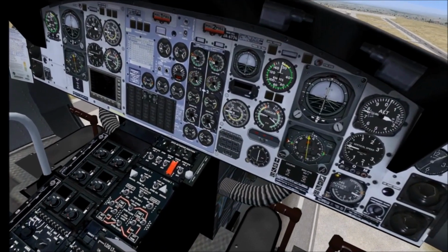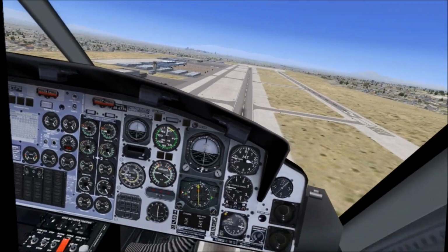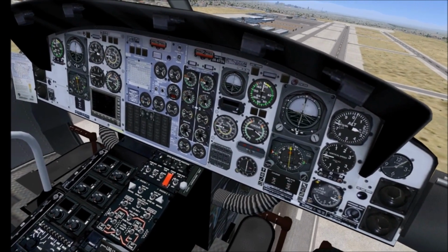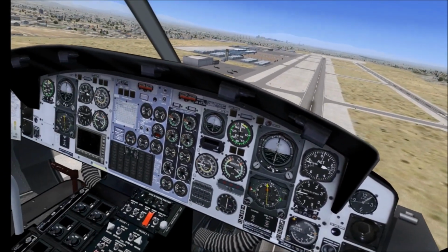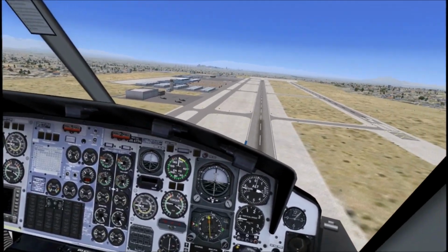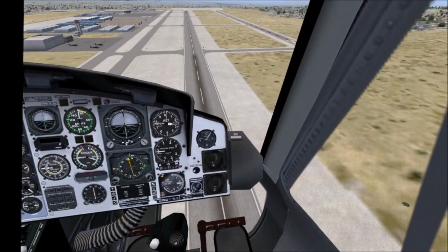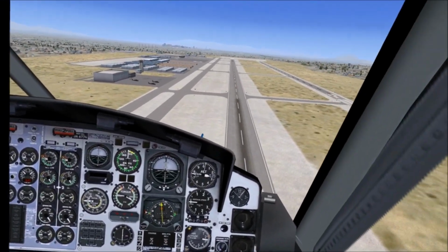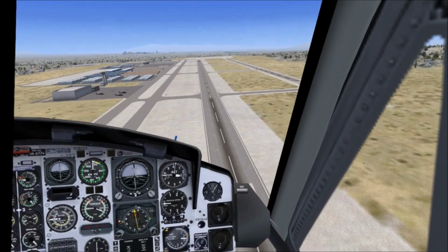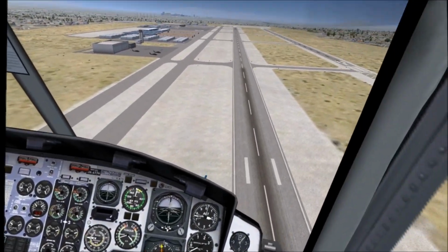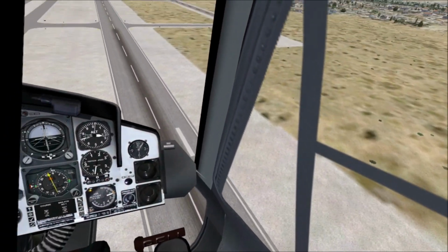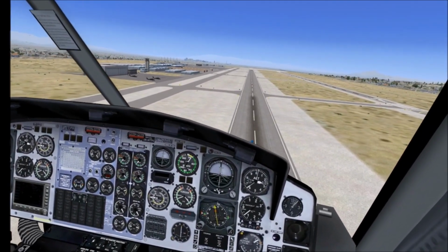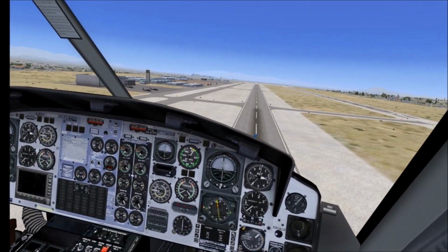Okay, so there's definitely an increase in power required to hover OGE, but it's not much. It's about 5%, which I would expect a little bit more than that, to be honest with you, because we were hovering about 60, so now we're about 65. So let's just confirm that one more time. I'm going to come back down to an IGE hover.